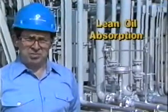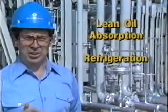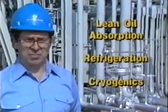The most common processes in the gas industry are lean oil absorption, refrigeration, and cryogenics. The appropriate process for a facility is determined by the makeup of the natural gas stream, available gas pressures, and the market for separate products.